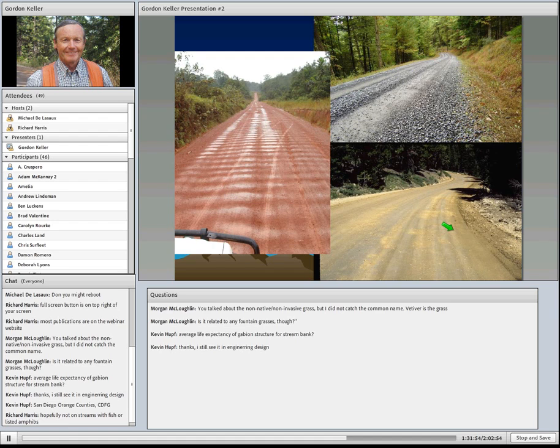It can cost more. I don't think it promotes traffic one way or the other, but it's more performance. And so it's this whole field of aggregate quality and management. It's kind of this thing of either you pay now or pay later. You pay up front and get better quality aggregate that performs better and needs less maintenance, or you get something that costs less initially, and then you have to put more money into road maintenance and maybe grading it more often. And that's a real trade-off we have on low-volume roads because you can go either way. It depends on the amount of traffic more than anything, and what materials are available.